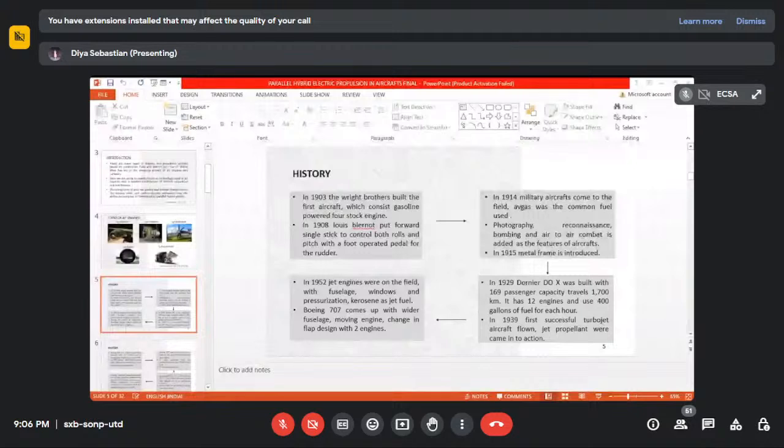Then moving to the sustainable fuels, there are mainly three types of sustainable fuels. They are biofuels, CNG and LNG, and liquid hydrogen. For biofuels, unlike fossil-based aviation fuels, the biomass to liquid method is used for production of fuel. Biofuel closely matches vegetable oil. In the case of vegetable oil, it has higher lubricity, right? So the biofuels also have higher lubricity, which gives much opportunity for the aviation industry to adopt it.